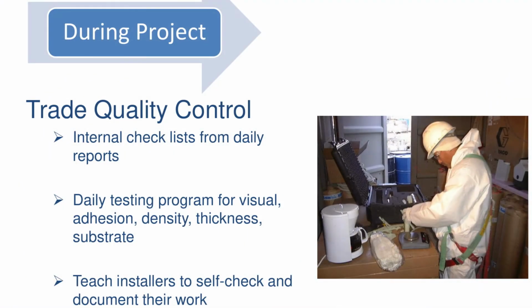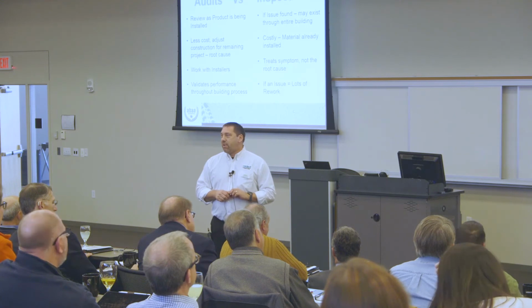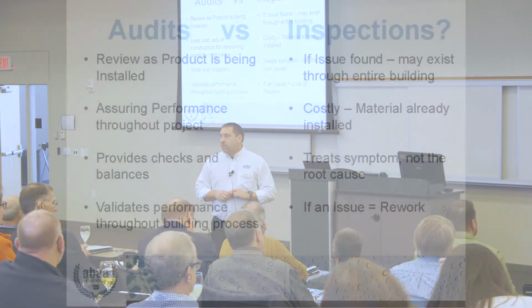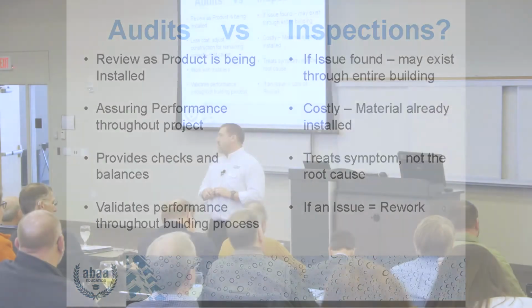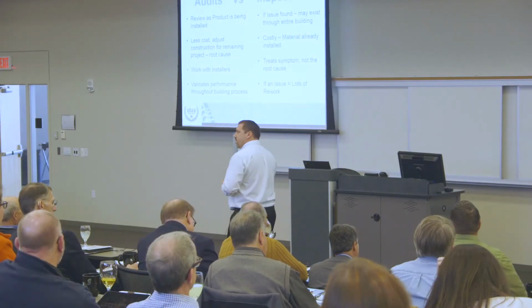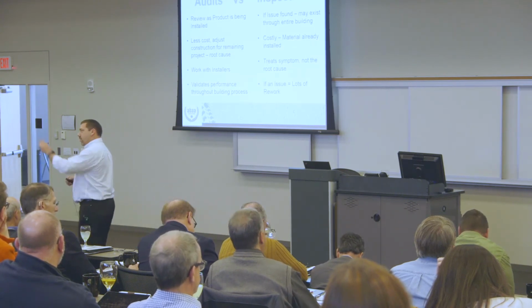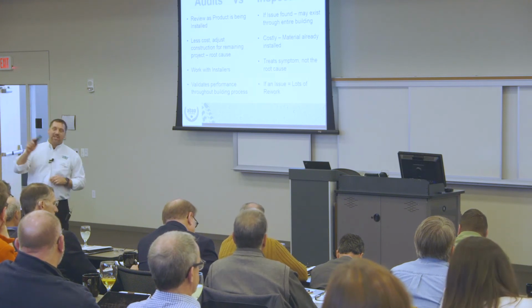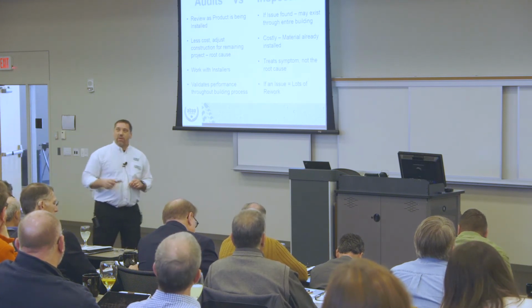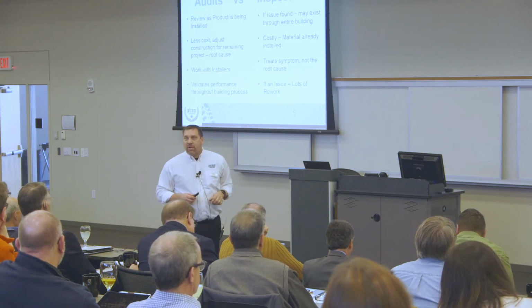Audit versus inspection, right? Two different things in my world. I see inspections normally happening at the end of a project, and somebody's just kind of checking, hey, yeah, it's done, but what happens if it was wrong at that point? I was on a project, I sent over the window specs to my superintendent 6 months prior. I circled the area because there was a new type of window out. The install directions looked almost identical to the old windows except for one little clouded area. I highlighted that, sent it to my super.